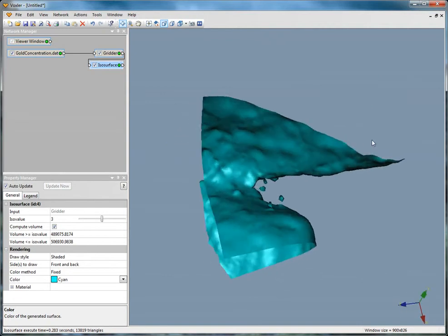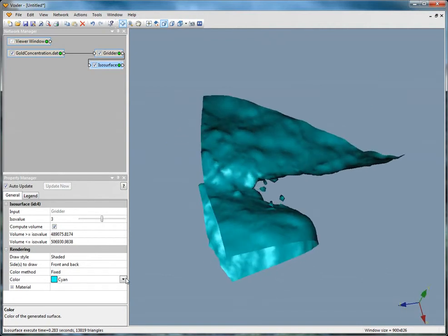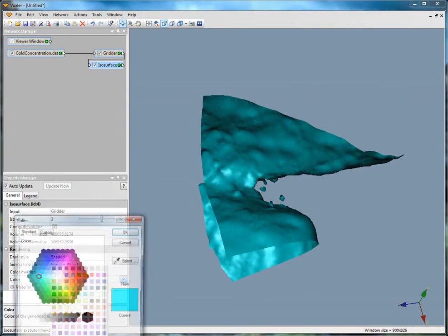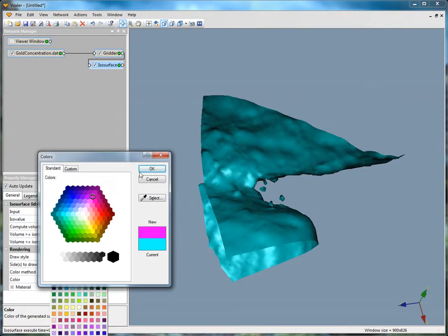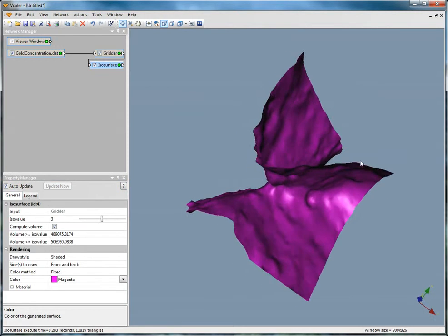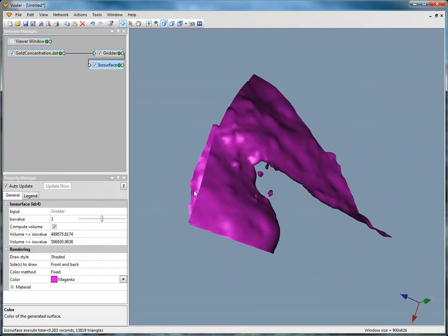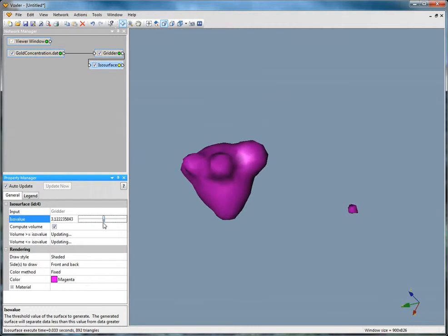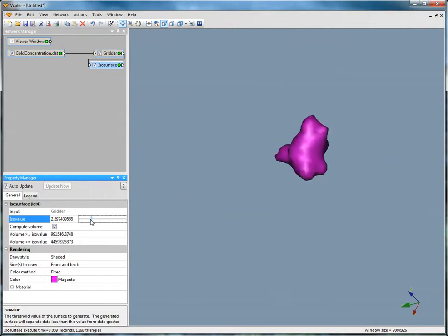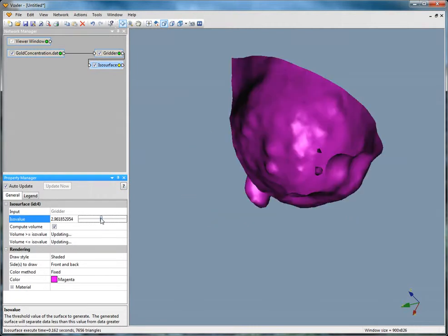To set a custom color, click the Other box at the bottom of the drop-down. Select the desired color and click OK to make the change to the isosurface. If you are showing multiple isosurfaces with different values, using the By ISO Value option with the same color definition will allow the colors to be represented by a single legend.